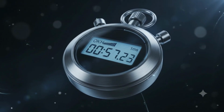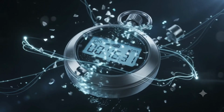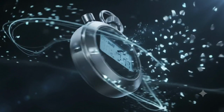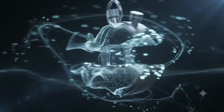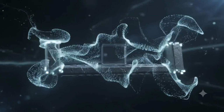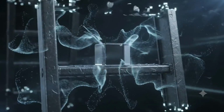Quick recap: TON delays turning something on, and resets if interrupted. TOF delays turning something off, letting it coast down gracefully. RTO remembers accumulated time across interruptions until it's manually reset. Once you know which behavior you need, picking the right timer instruction becomes automatic.